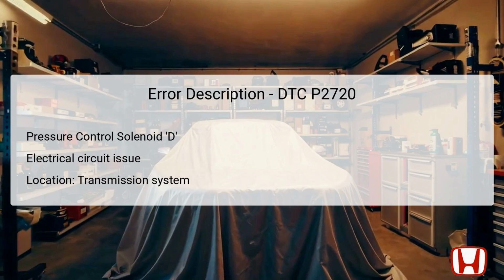and repair. DTC P2720 concerns the pressure control solenoid D, which is integral to managing the pressure in the transmission. This solenoid is located within the continuously variable transmission assembly, typically integrated into the valve body. Its role is to modulate hydraulic pressure, which directly influences how the vehicle shifts gears. The electrical circuit is vital as it communicates operational commands to this solenoid from the powertrain control module, or PCM. An issue in this circuit signifies a failure in either the communication link or the solenoid's function, highlighting the need for a thorough investigation of wiring and connections.